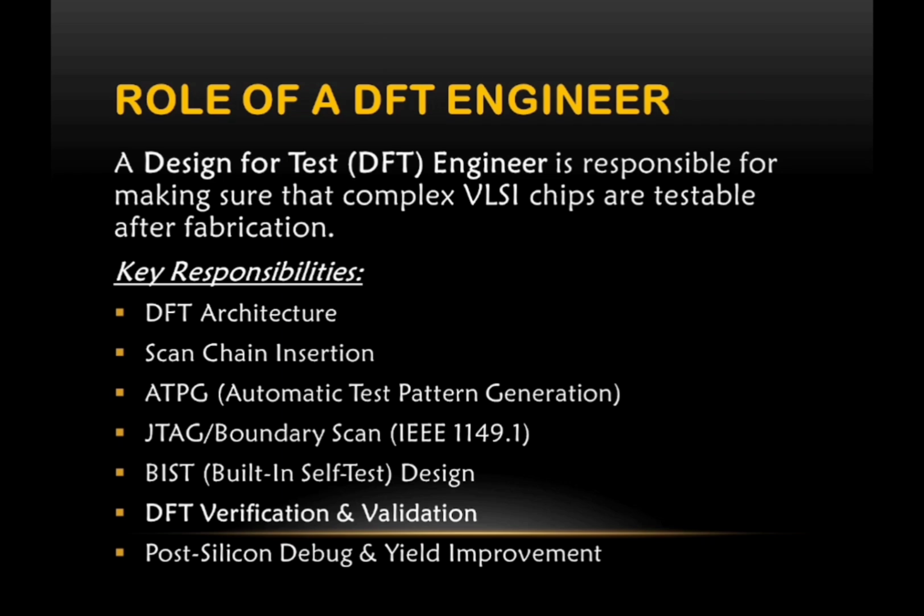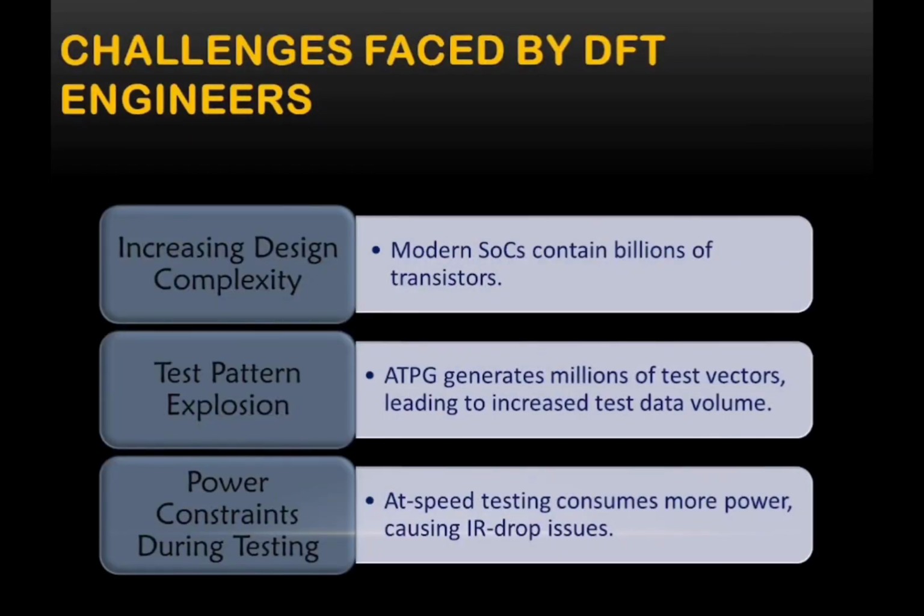The next responsibility is DFT verification and validation. In this process, the DFT engineer ensures scan-based testing, MBIST and JTAG functionality before tape out of any particular chip. And the last responsibility is post-silicon debug and yield improvement, collaborating with the automated test equipment team for failure analysis.